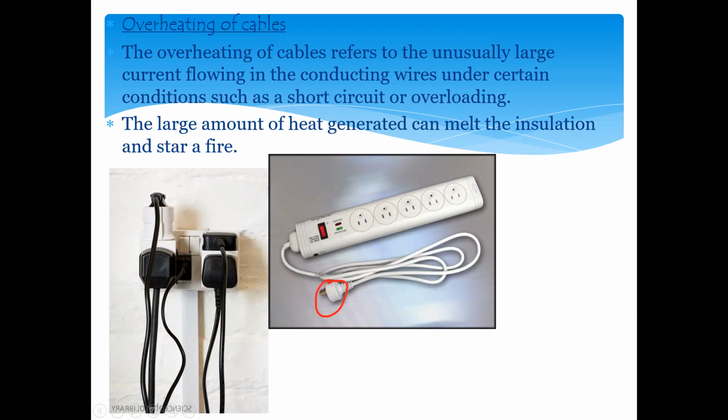So what is the disadvantage of using many devices connected to one socket? It produces a lot of heat. As a result, when it produces heat, that heat can cause a fire. So overheating of the cable: when we draw too much current from the circuit, it may lead to damage due to heat. It might melt the insulation and then start a fire.